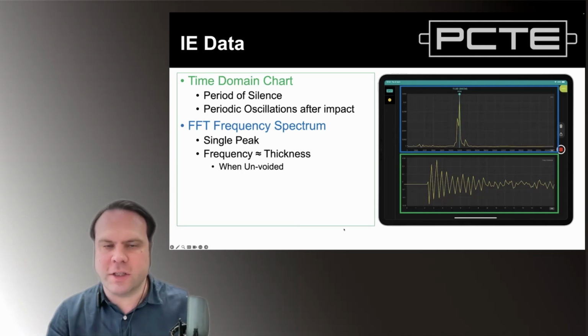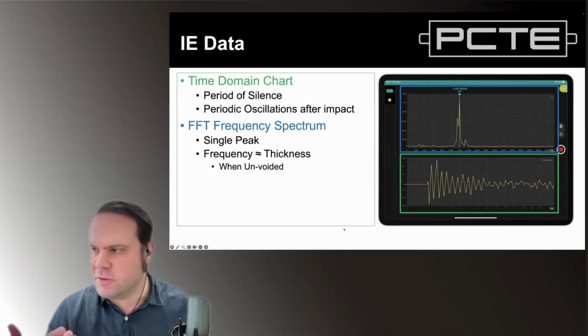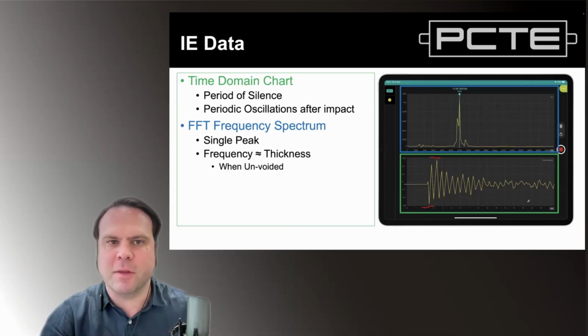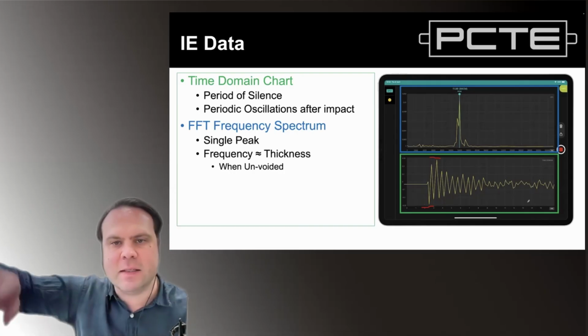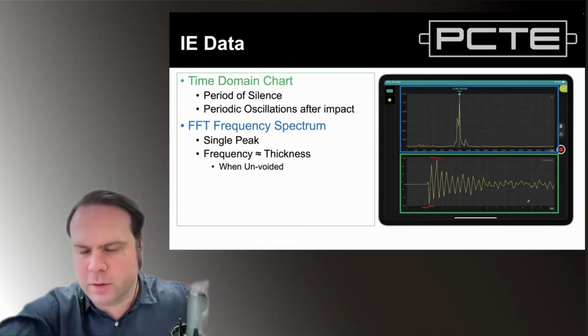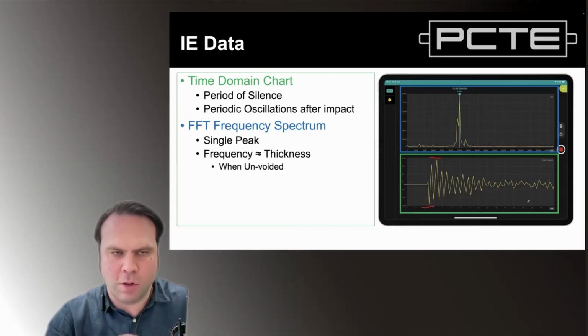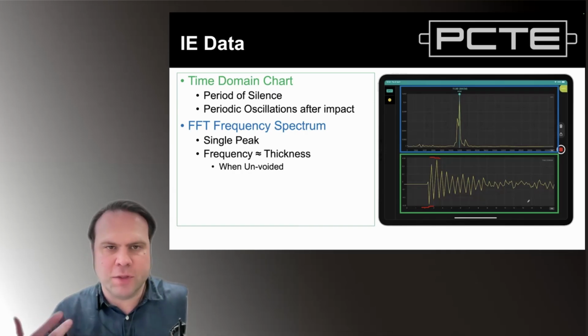Whenever you're recording sound or signals, it's very important that your waveform doesn't go below or above the maximum of your chart. So we can see in this chart, we've got a repeating signal, but it hasn't gone below the lowest point on the chart or above the maximum point on the chart. If it did so, that would be called clipping, and it would ruin the test.